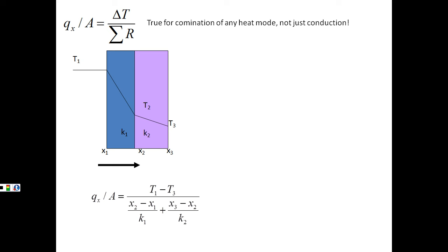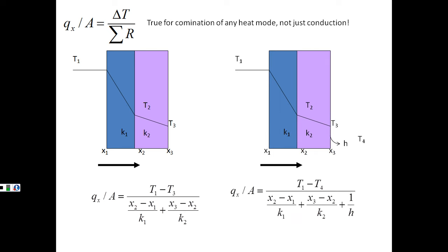So now if, for example, we have glass and we have metal and then we have air going out to some ambient temperature T4, being T infinity, some distance away, we can think about this as an additional resistance term. And usually it's pretty small, right? So most of your heat transfer is occurring through the conductivity, but then you can have this additional term where you have basically a skimming off of that air layer from the surface, which is adding an additional resistance.